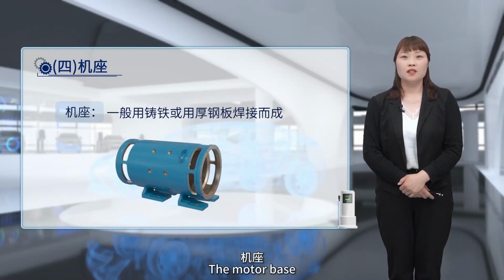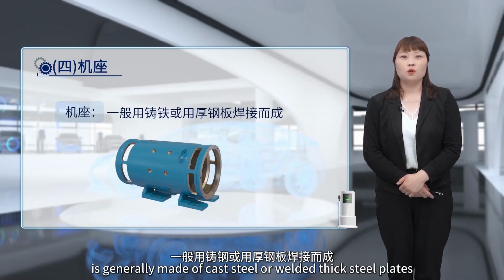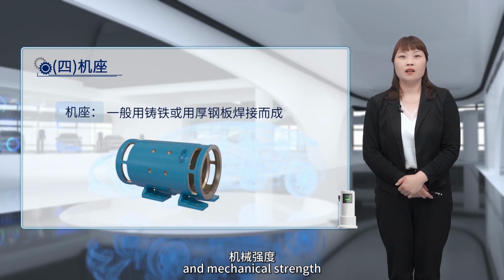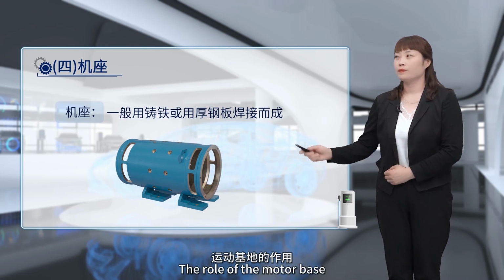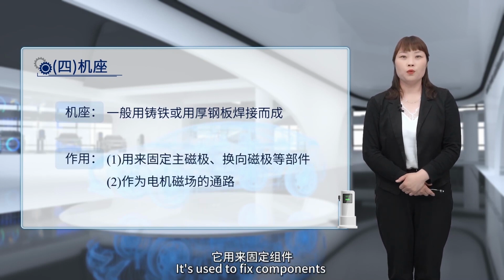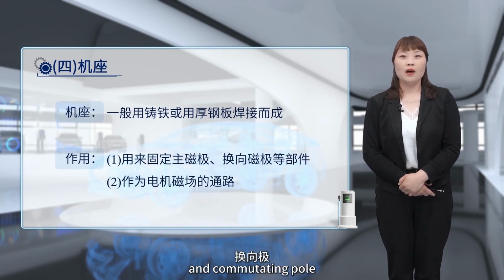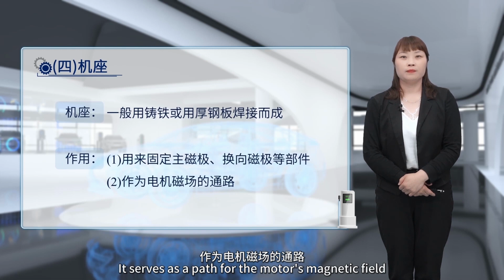4. The motor base is generally made of cast steel or welded thick steel plates, which have good magnetic permeability and mechanical strength. The role of the motor base. 1. It's used to fix components such as the main magnetic pole and commutating pole. 2. It serves as a path for the motor's magnetic field.